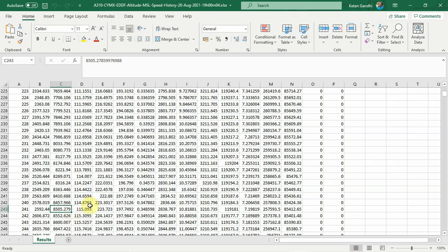Now based on that we'll have a particular increase here. This is true airspeed which is giving 223.73. This is actually incorrect. This is the calibrated airspeed that gives the correct answer, because this is incorrect. If you calculate based on 170 knots flying at 8,500 feet with 2% increase in the IAS speed, it is showing 223.73.